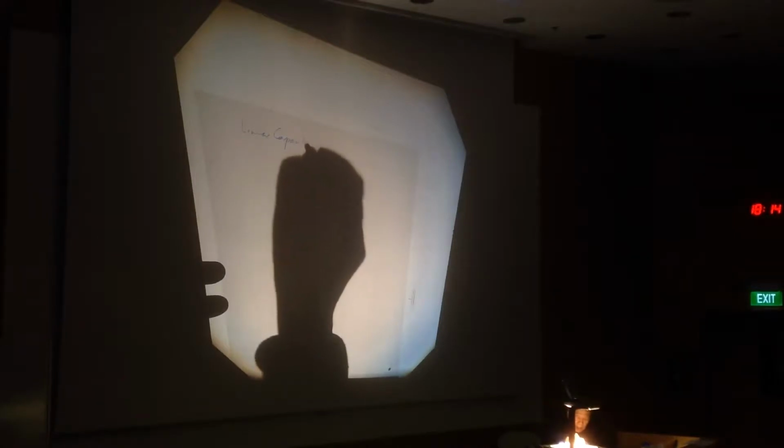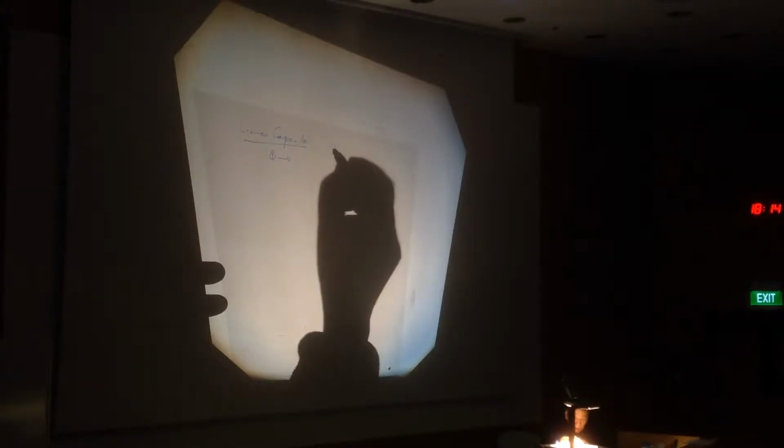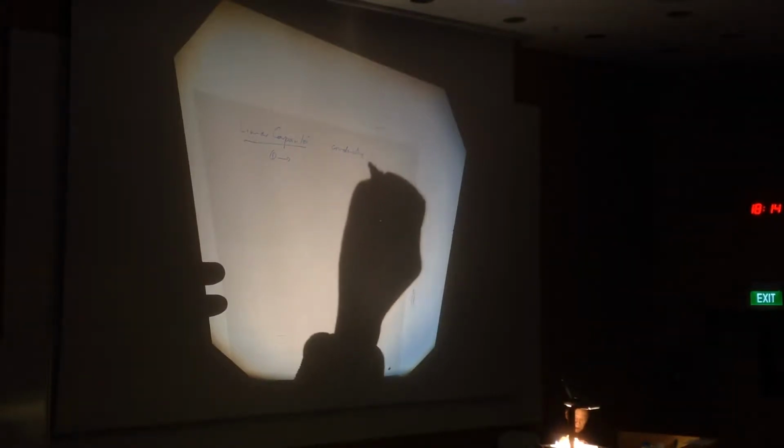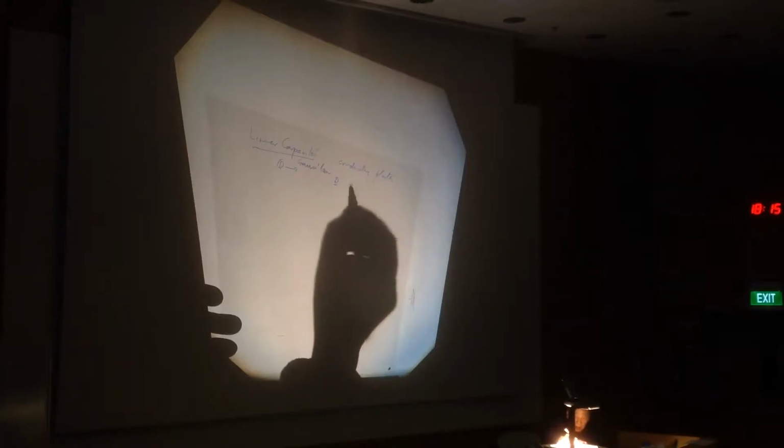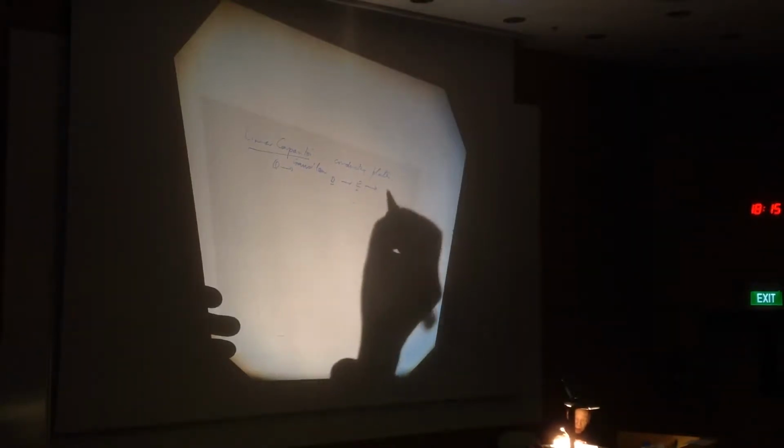Capacitance: I'm talking about a linear capacitor, a normal capacitor. You put a charge of Q on a positive conducting plate. For Q, Gauss's law gives you D, from D you get E, and from E you get the voltage, positive to negative, minus the integral from the minus to the plus plate of E dot dl. This is the traditional way of doing it.